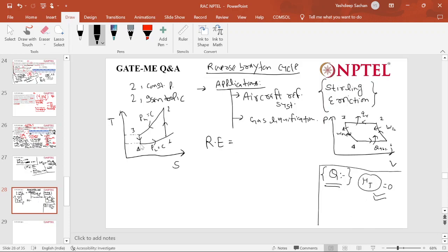Okay, first I will let you know. This would be the inlet of the cycle, same as VCRS. This is the inlet of evaporator, and this would be the exit of evaporator. This is the inlet of compressor. Point 2 would be the exit from compressor, and from 2 it will go into the condenser, and 3 is exit of condenser, entry of turbine here, in place of the entry of expansion valve or throttling valve. Here inlet of turbine, and 4 is the exit of turbine. Now naming of each is clear or not?